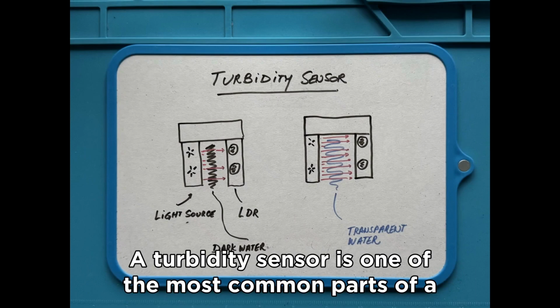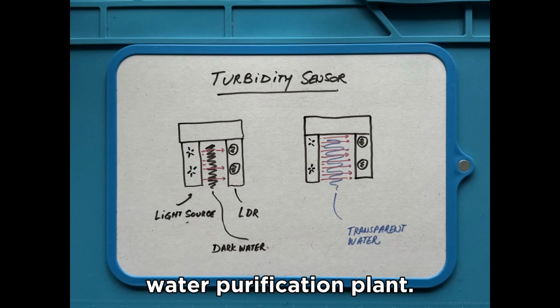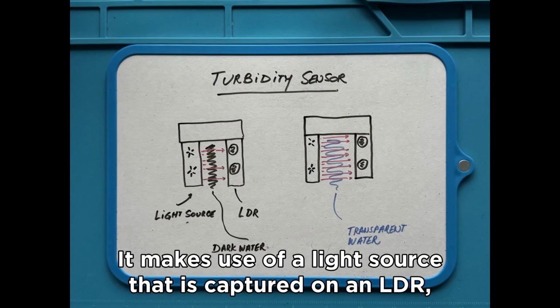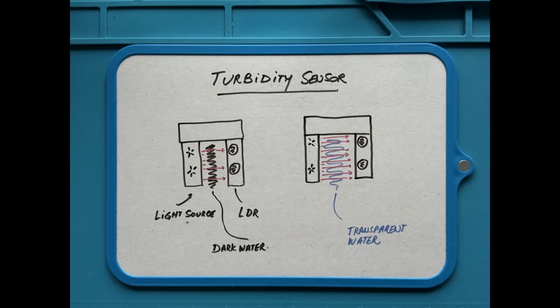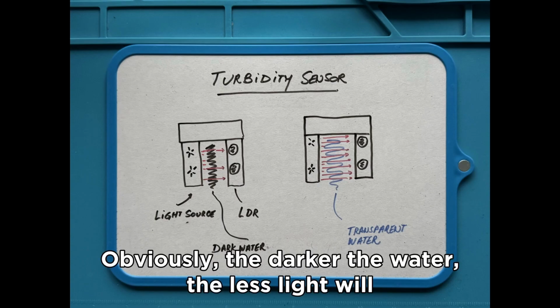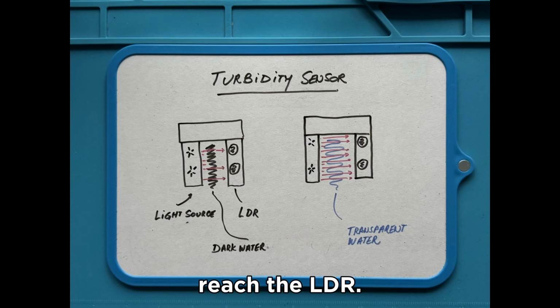A turbidity sensor is one of the most common parts of a water purification plant. It makes use of a light source that is then captured on an LDR, which stands for a light-dependent resistor. Obviously, the darker the water, the less light will reach the LDR.